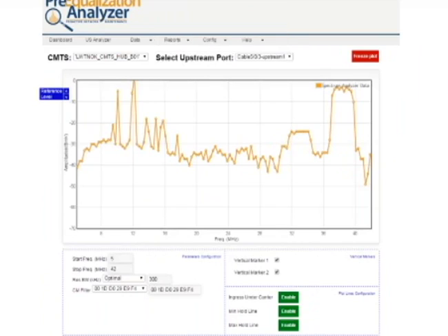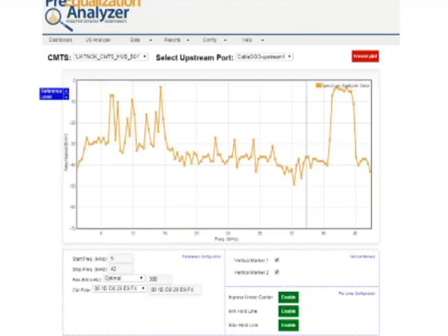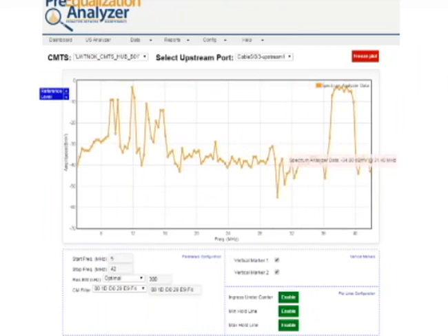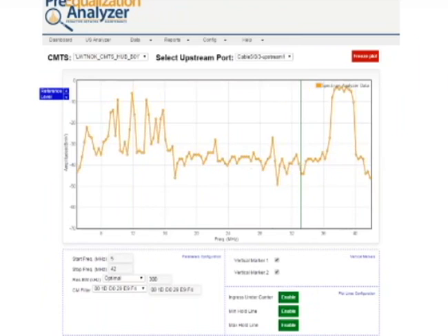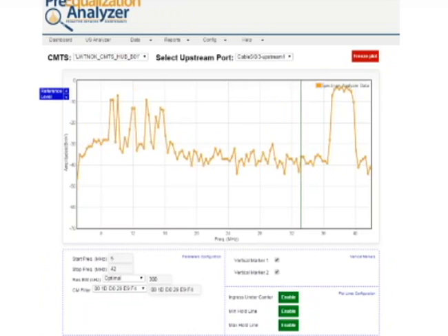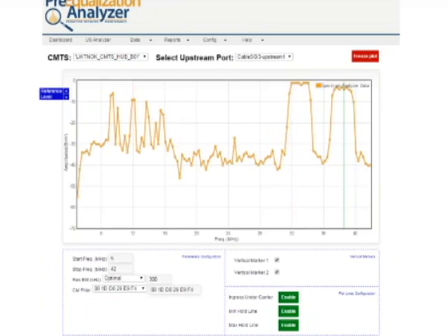Yeah, so what we're seeing is basically a specific cable modem. We're looking at our entire upstream frequencies. You can see down here, 12 to 16 megahertz, we have all of the CB band noise. And you can see we actually have some cable modem transmissions on another frequency because of how we've got our return path, or excuse me, our combining plant set up. So this port is actually seeing both the modem that we're looking at and modems on a nearby frequency.